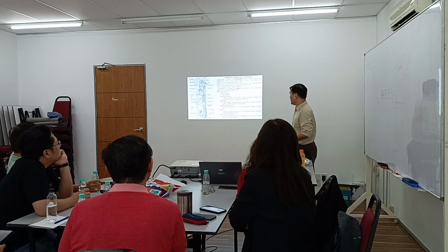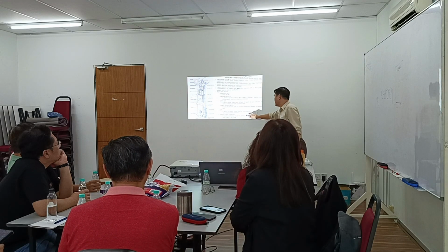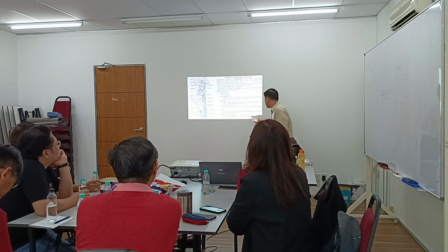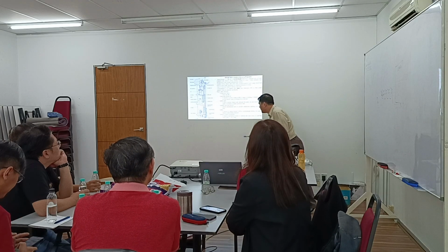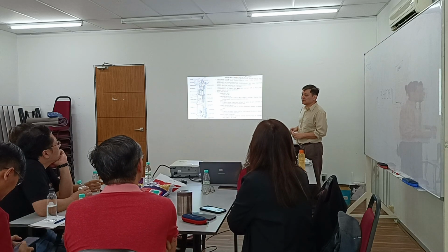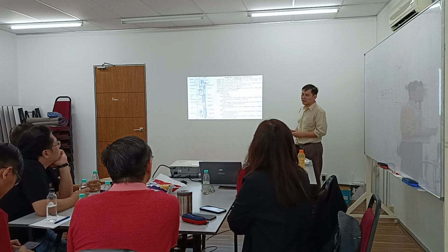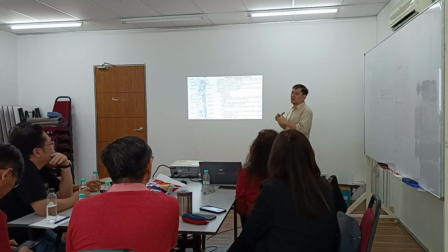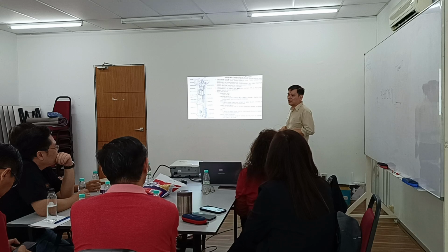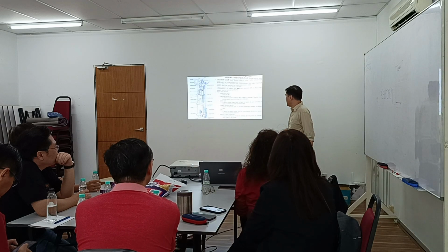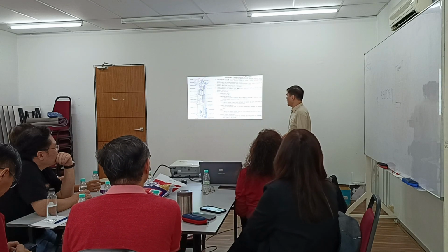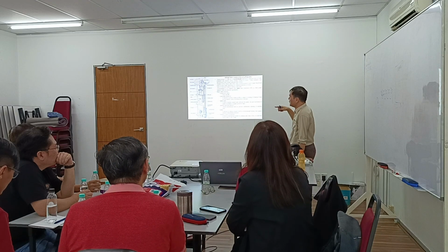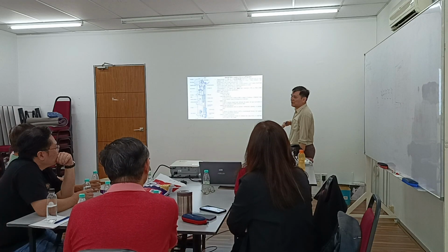Alright. Then the braking system of the machine, this is also very important. It's an electromechanical system to release and to stop the motor. So the keyword is electromechanical. It will cut off the electrical supply, then after that it will engage the so-called mechanical force. It could be drum brake or disc brake. For the recent motor lifts, they use the disc brake. For the conventional gear motor, they use the drum brake.